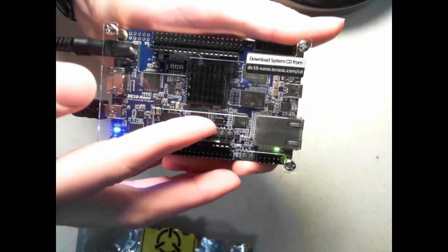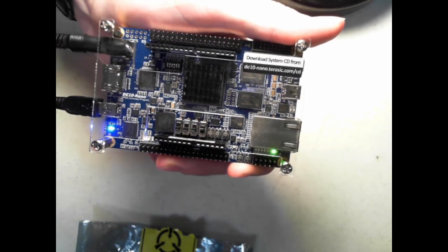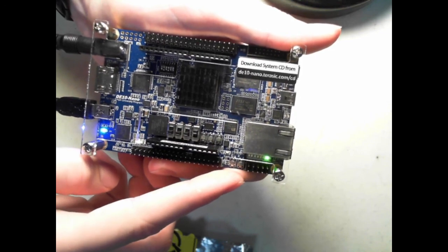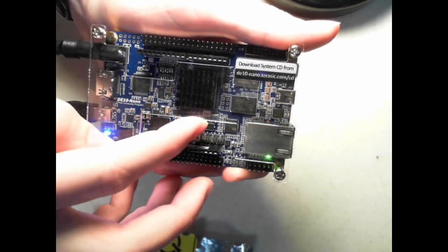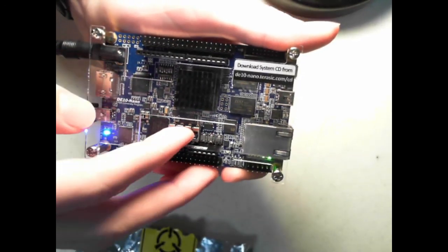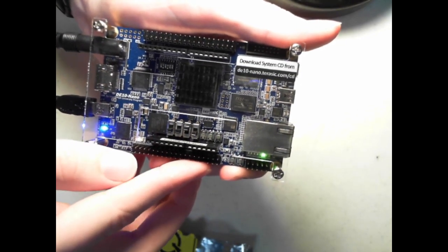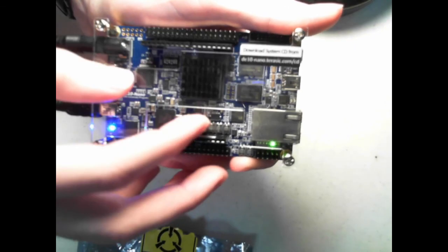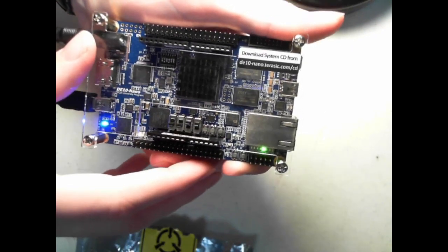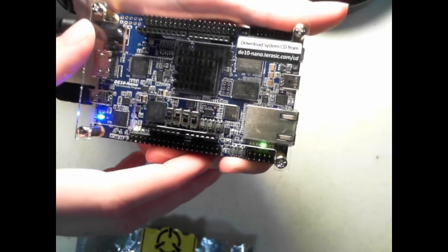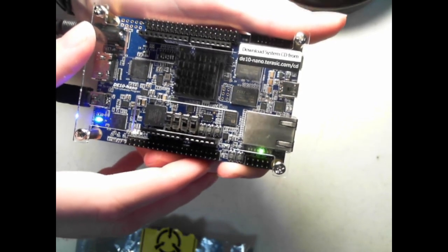If I flip up this first one, now we move to the left one LED. And then if I flip up only the second one, then we move from the right to the left 2 spaces. And if I flip them all up, we move 4 spaces to the left. And yeah, that's our decoder.